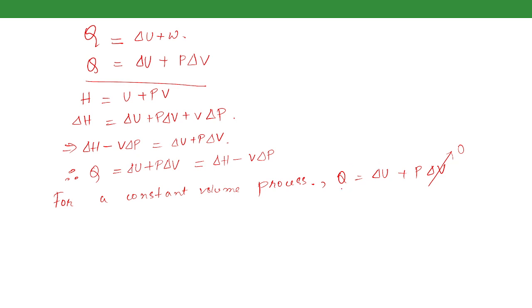So this heat can be written as what? That is the mass of the substance, the specific heat at constant volume of the substance, and the rise in temperature. This is the mass of the substance, and Cv is for unit mass and unit degrees. So when we multiply it with the total mass and the total rise in the temperature, we will get the heat required for causing this change in temperature for this mass of the substance. And this equates to delta U.